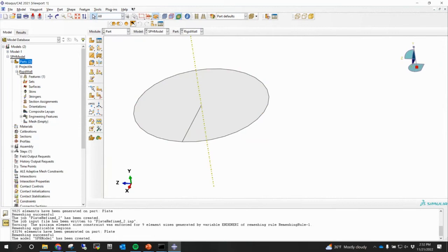We have to add a rigid reference point. So I'm gonna go here to reference point, and I'm gonna create that reference point. Later on, we've done this several times, we have to create a constraint between rigid bodies and reference points. In that way, we only apply the boundary conditions to the reference points, correct? Anyone remembers that?